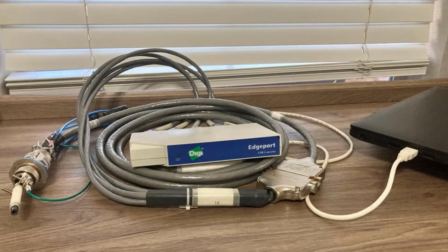We're covering the installation setup of the EDGEPORT device. It's needed to download the Honeywell HTF 7000 series engines. Here we have a view of the box and associated cables that are needed to perform this task. One important note is that the USB port on the laptop that has to be used may need the setup done on each individual port and should be checked using the same procedures.